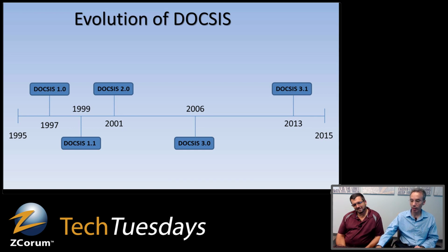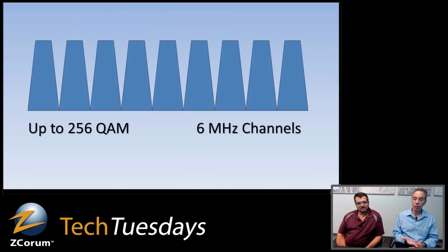So, just in general, really nothing's changed in how TV is done. It has been done the same way since analog broadcast TV: 6 megahertz channels, or 8 megahertz if you're in Europe. That went for analog broadcast TV, analog cable, and digital cable, up until 3.1. You had these 6 megahertz channels with guard bands on each side so they don't overlap.